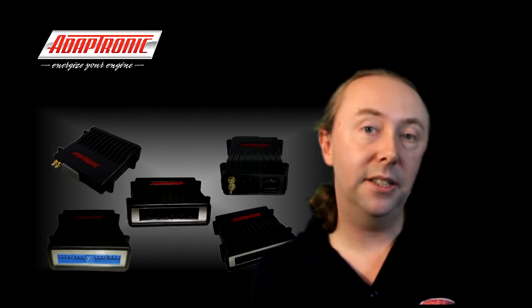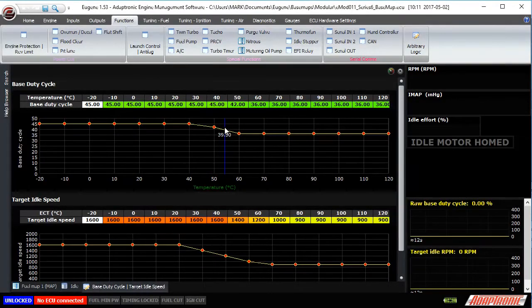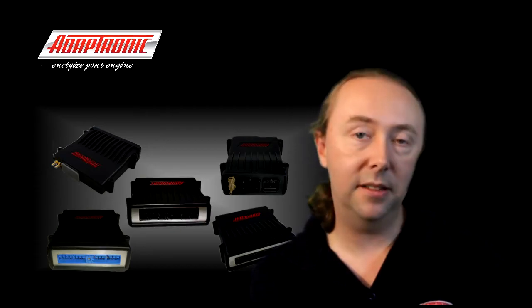Now, once you start the engine, you can then adjust the base idle duty to get the correct idle speed as the engine warms up, so you can do that at each temperature point. Then you can extrapolate the ones from the top and from the bottom, so as to fill out the table.